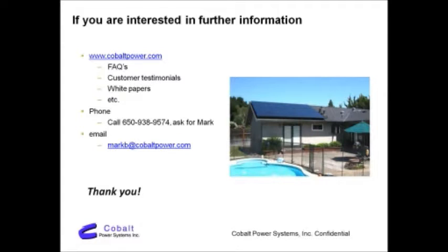Okay, question from Z. What happens if after the installation of the solar panel on existing roof, I need to replace the roof under the panels, let's say 10 years later? Great question. When we do what we call our site visit, which is where we meet with the customer and we measure the roof and measure the shading and have a little dialogue about what their goals are for their system so that we can custom design the system to satisfy their needs, we always evaluate the condition of the roof. And if the roof only has a few years left on it, we will recommend that they replace the roof before they put on the PV system.